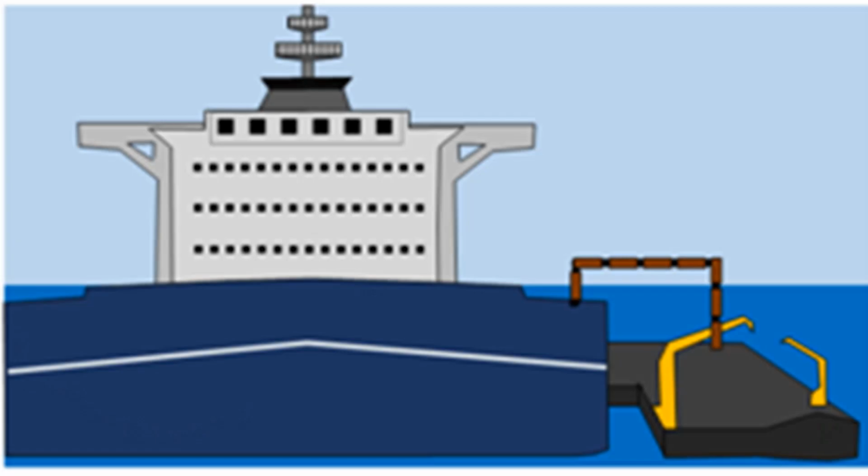The fuel that is supplied to the ship is deficient in sulfur, and the secondary means of applying the control is, number one, on board, the fuel can be blended with some low sulfur fuel so that the final fuel that is burnt is low in sulfur, or probably some additives are added to the fuel, and when these additives are added, the final sulfur content is low, or you have a scrubber unit fitted on the ship.